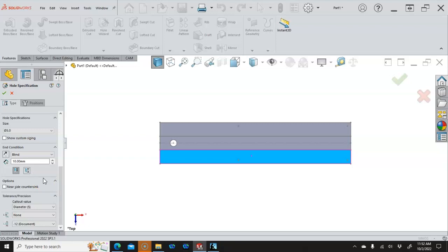If this is going to be a reamed hole, so we have 5 millimeters, which is .197 in inches, then I might want to do a .196 to .197 and make that a press fit. So that's one possible, but that's where the callouts and the additional tolerances come into the mix.